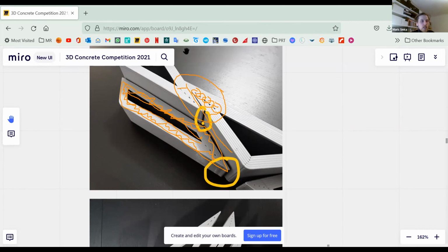As you understand, this is an overhang. It doesn't support itself, so I need some reinforcement here. I need at least 2 layers in between. So draw this element, then 2 layers of this, and then 10 layers. Flip it over in the STL file, so we can just print it.